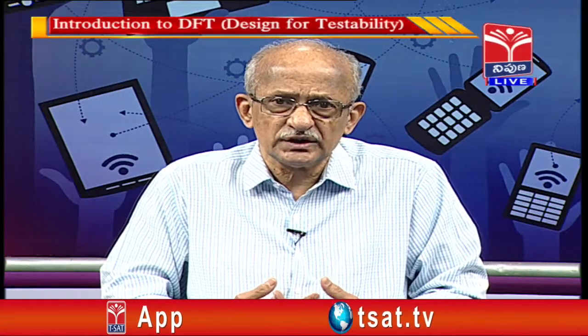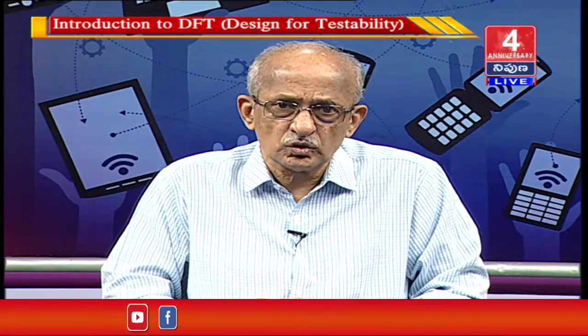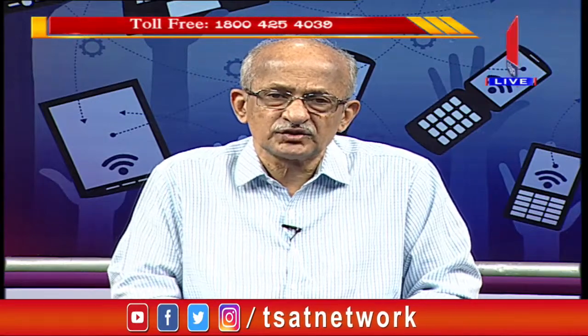There might be no stuck-at faults. Every node is toggling from a 0 to a 1, but not in the required amount of time. It's like an engineering student who is expected to come out in 4 years, but some students may take 5 years because of backlogs. They are not stuck in engineering, but they are taking a longer time than the prescribed time. Therefore, there is a delay defect.